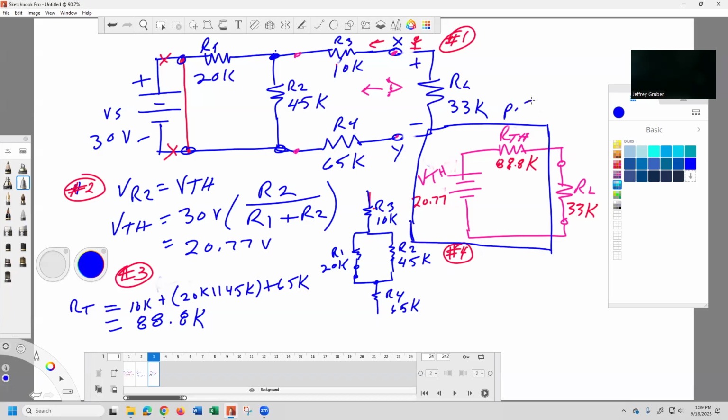So that's like a power supply, and then this is the load. These are the terminals on the power supply. So there's some series resistance in there. The higher this is, if it's high, then you're not going to be able to regulate very well because you're dropping a bunch of your output across it. You want it to be low. We'll talk about that when we talk about power transfer.